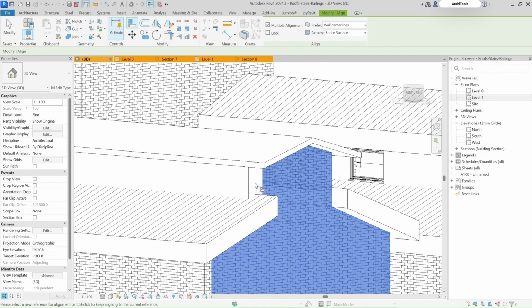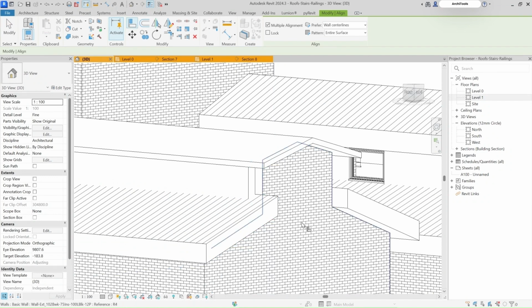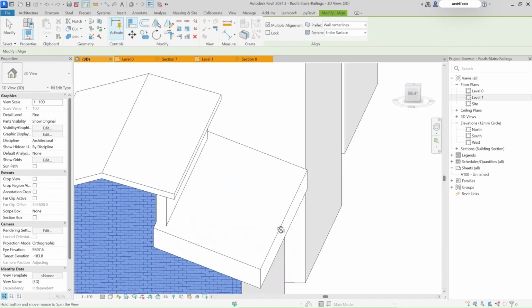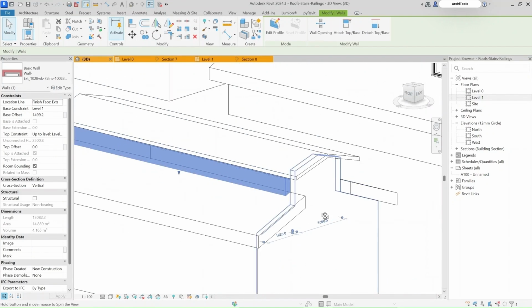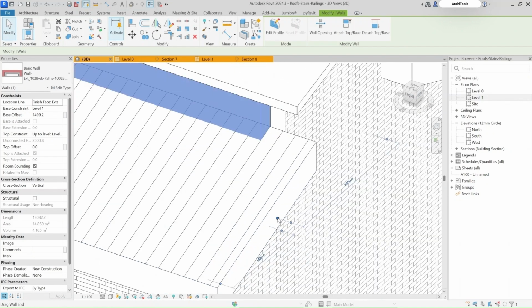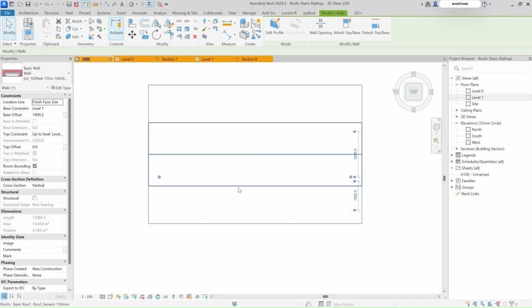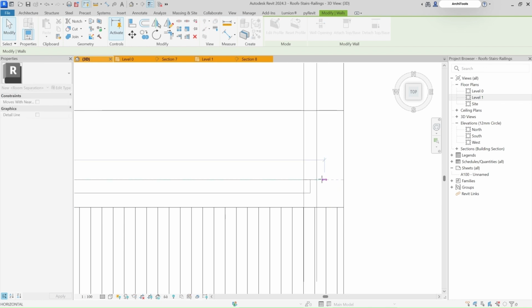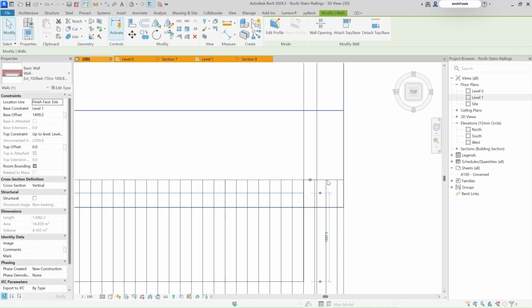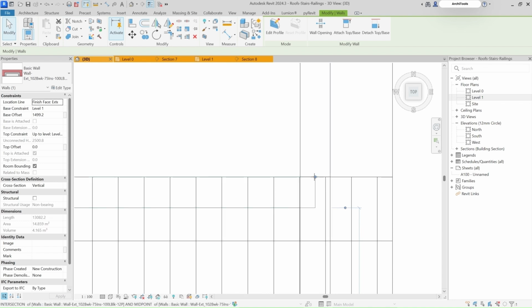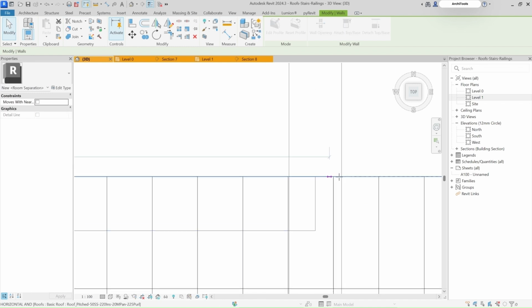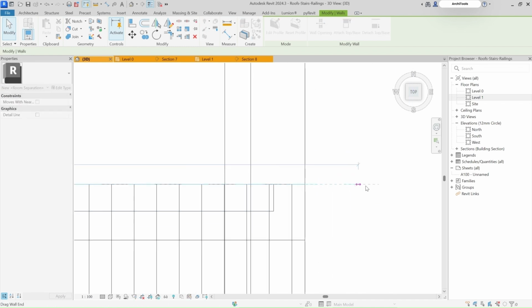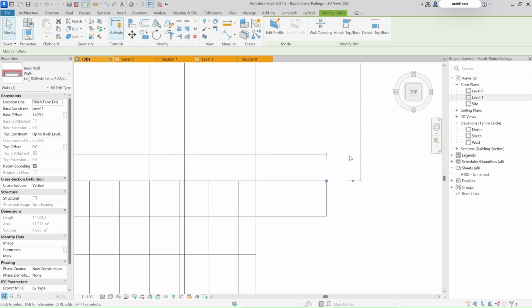I'll just move this part where I'll align this end with this. As you can see, it is not aligning like over here. So what you can do is either go onto the top view and try to drag it like this. Going into WF for wireframe, as you can see, it is still not attaching. I'll move it a little further and again try to join it. It's still not joining, so I'll drag it further up till I get a clear region.